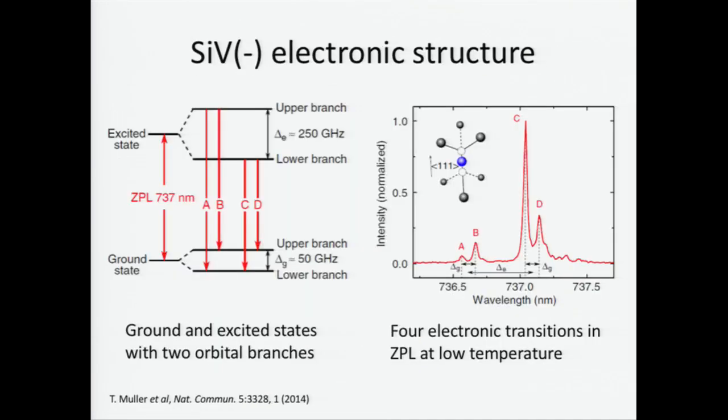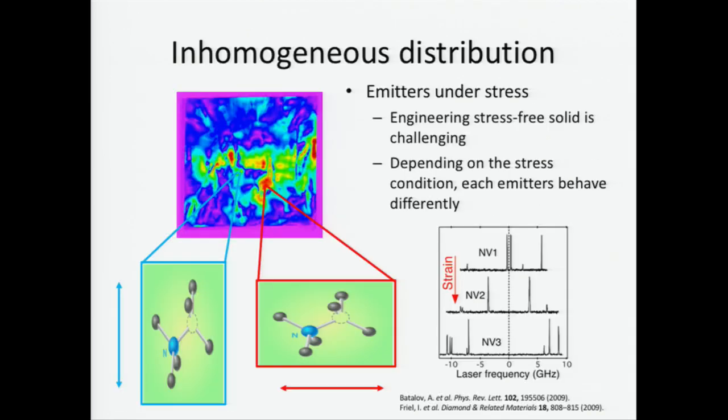So let me go here. They're in diamond, and they are actually stretched like this. The way you measure strain is, without any stress you have a perfect crystal, and then if you stretch it by 1%, the strain number is 0.01. So delta L over L is the definition of strain, although it becomes a tensor. With this device, the level we can reach is about 10 to the negative 3. Basically, it's 0.1%.